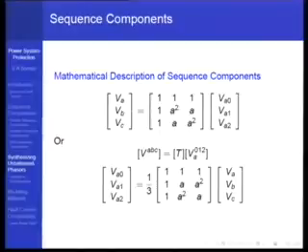If this matrix T was not invertible, then when you went from the 0, 1, 2 domain to the ABC domain, you would have lost information, and therefore you could not have come back to this particular place again. When you say a transformation, you change domain without loss of information, and then you can come back to the original domain without any loss.